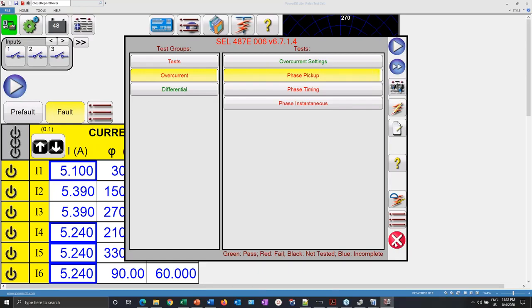Now, another thing I will mention is that when creating the templates, you can actually utilize the simulation mode. Before you connect to the relay test set, you can use the simulation mode, create your template, and script everything you need over from your settings tab into your test template. Then it allows you to run the test to make sure your calculations and your values are correct, and then you can run it on a relay, or pass it to other technicians to do in the field.